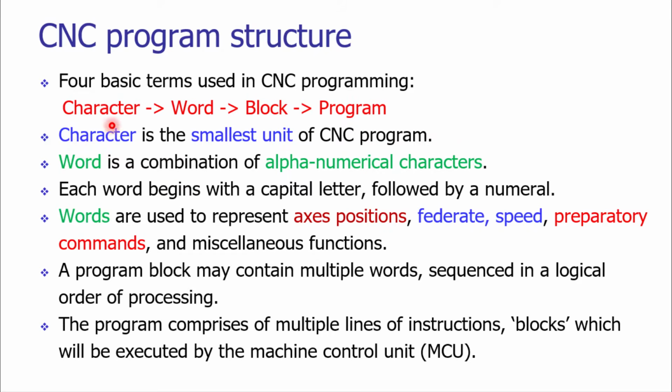When we combine various characters, a word is formed, and when we use the words in a logical order, we get a block. By putting various blocks together, we generate a program, and that program carries out the CNC operation. It may be a turning operation or a milling operation.